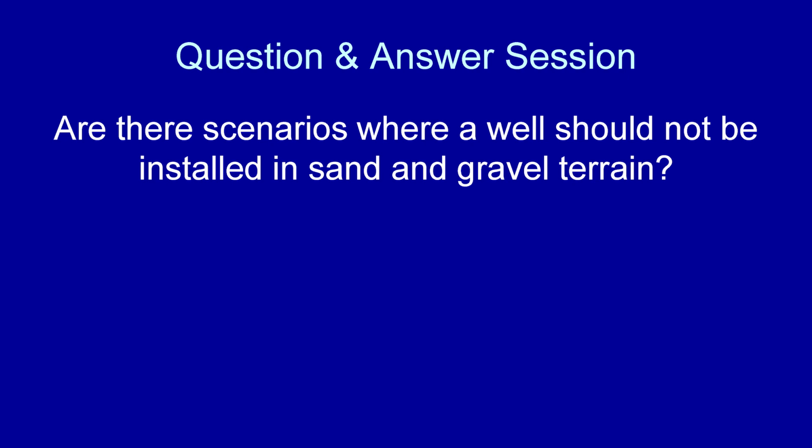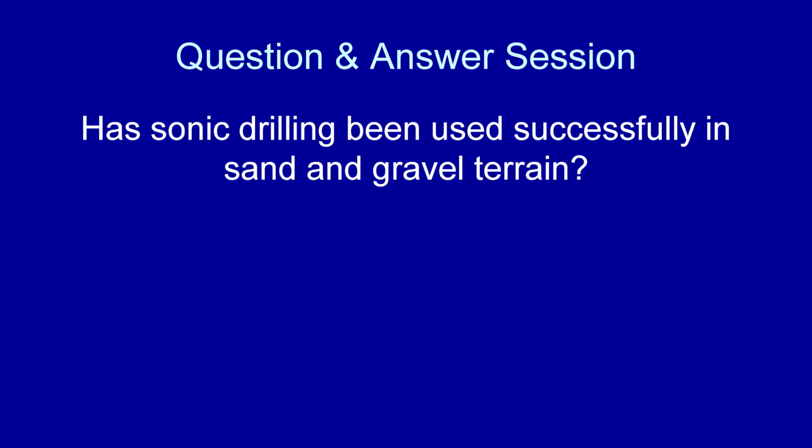Great, thanks for that. A couple other questions we have coming in. One is, has sonic drilling been used successfully in sand and gravel terrain? Yes, it has. As a matter of fact, sonic drilling, again, if you have reason to believe you are going to have major boulders and or cobble complexes that the 2.5-inch diameter driven well cannot penetrate, the sonic rig is certainly something that is excellent.